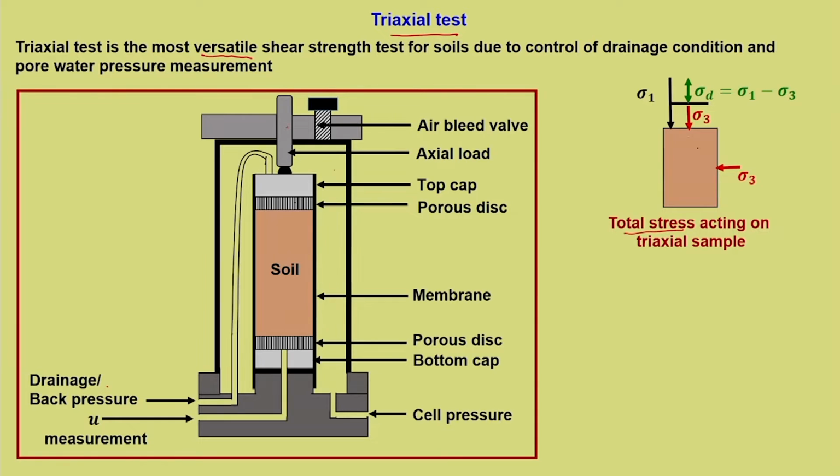Now, in triaxial testing, it is important to understand what causes failure. So, initially there was a confining stress sigma 3 all round. This stress will not partake in the process of failure, because this is an isotropic stress condition, a mean stress condition where all round stresses are equal. Now, this creates volume change, but not shear stress within the soil. This we have already discussed.